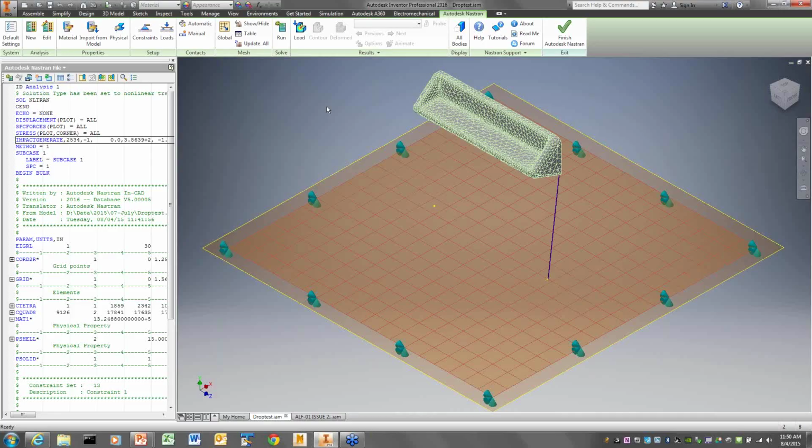This little shelf thing was killing me because I exported it in English units and I re-imported it into metric units. I was like, what is going on? Because my mass was in metric tons and my distances were in inches, because I had just totally forgotten to do it. And like I said, it was immediately obvious I was getting wrong answers, and so my validations did not hold up. It turns out it wasn't that I had the wrong mass or the wrong anything. I had just totally hosed my units.